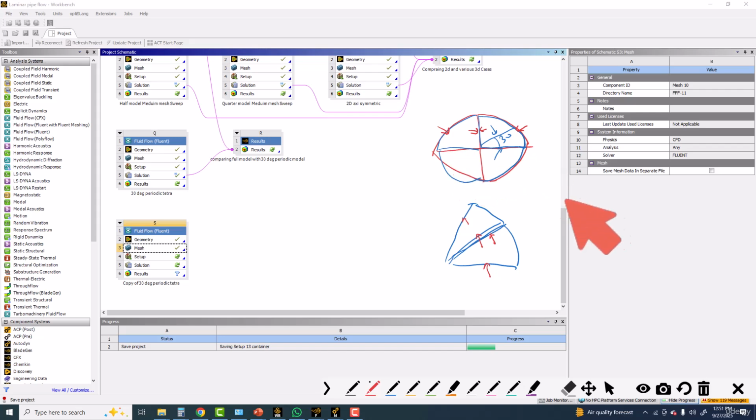It's only possible then. For example, if I have a rectangular pipe, in this case I can only apply the symmetry on these two boundaries. I can make the model one fourth of the whole geometry. But I couldn't make it periodic here, because if I rotate this geometry, I could not get the same geometry. So in rotation, this will be a different thing. This rotation is only possible when the boundaries are circular. Circular geometry can have periodicity. So I am taking the benefit of the circular geometry here, and I'm going to model the 30-degree sector, and I will see whether we get the same results or not.